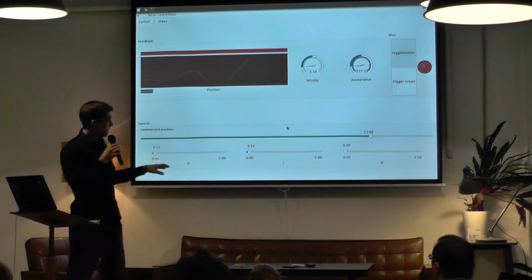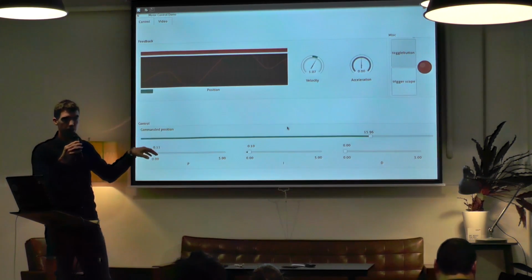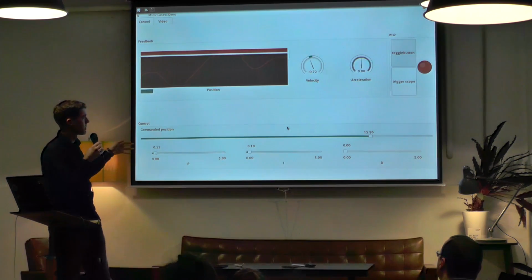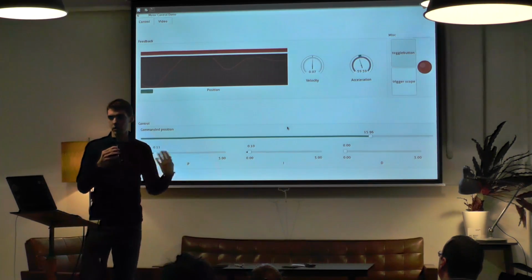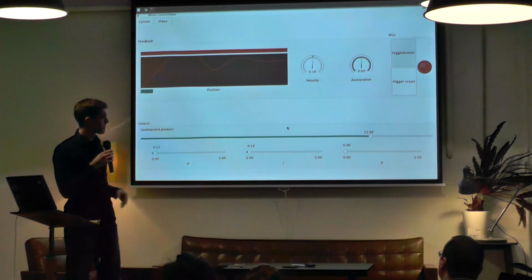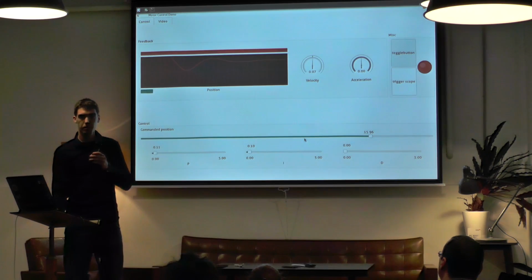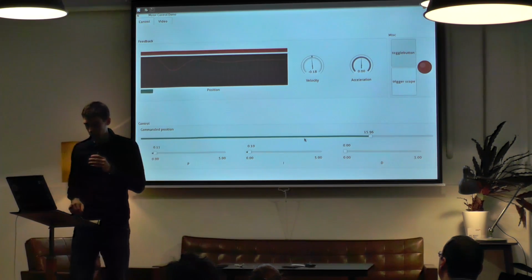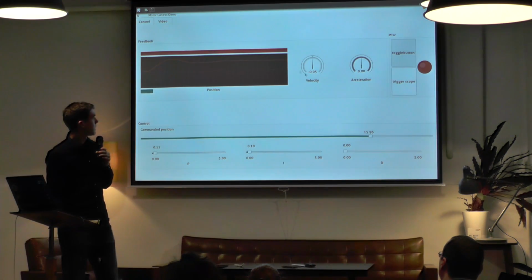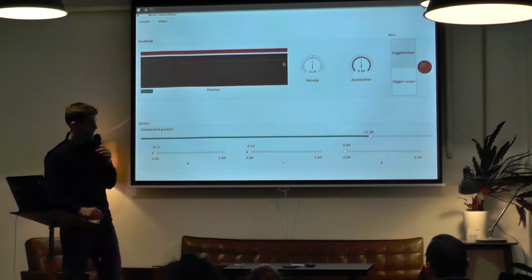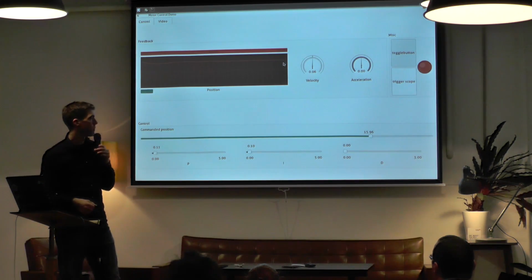And these user interfaces can be created just with a few clicks or a few lines of code. There are dials and sliders and so on available. And these sliders, for example, represent a pin in the configuration. In the configuration, this would be, for example, the position pin, and the position pin is, as we have seen in the presentation, connected to the PID loop, which controls the servo motor.